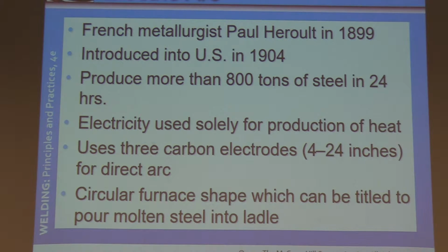They produce a direct arc with 3-phase power and are supplied with electric current through a transformer. Newer furnaces have electric capacity between 900 to 1,000 kilovolt amps per ton of steel being processed. This could amount to 42,000 amps, thus a very high energy arc. Keep this in mind next time you're welding at 100 amps or less, okay?